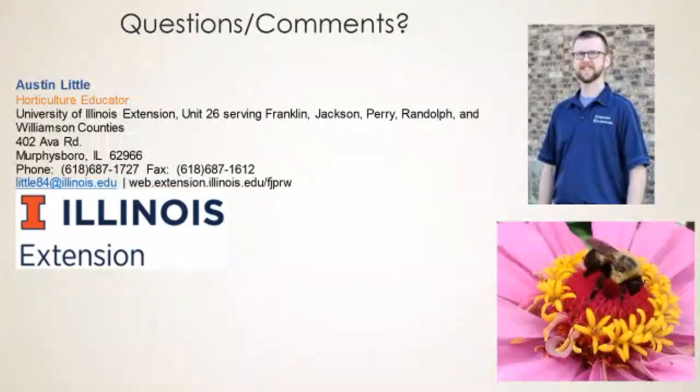They're not really invasive or at risk of that, but they're used because they cover green roofs really well. They're shallow rooted, and they offer those benefits of recycling water, evapotranspiration, heating and cooling benefits, and all of that. Now, they don't have quite the same impact on pollinators, so that's one drawback of those. So there's some benefits and some drawbacks, but sedum is going to be the most commonly used for just the ornamental vegetative ground cover.